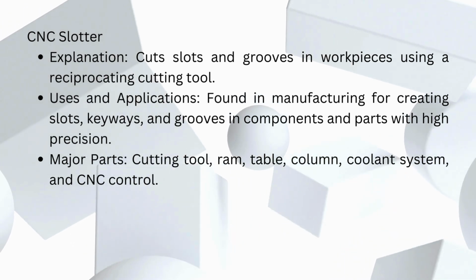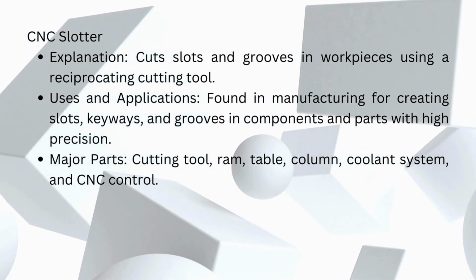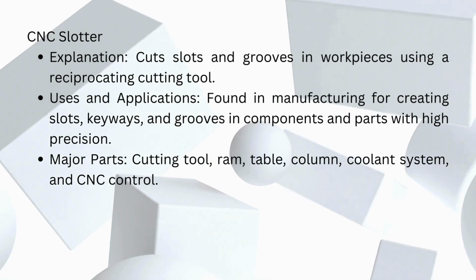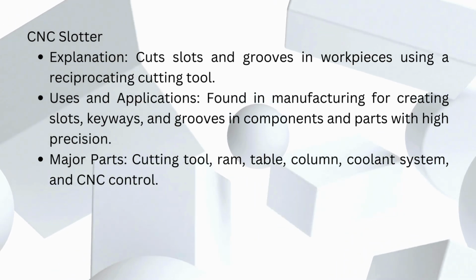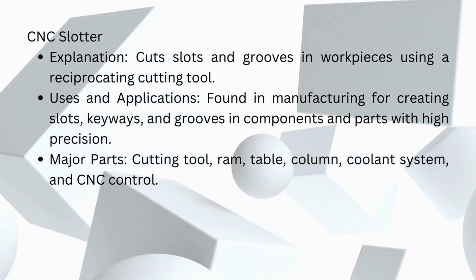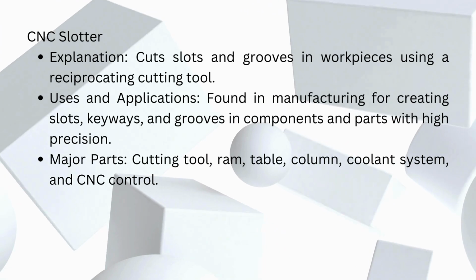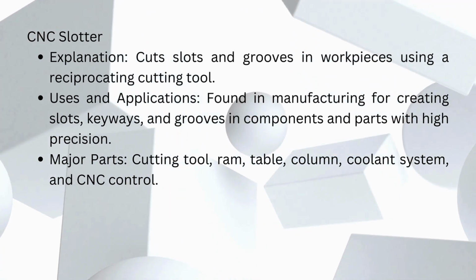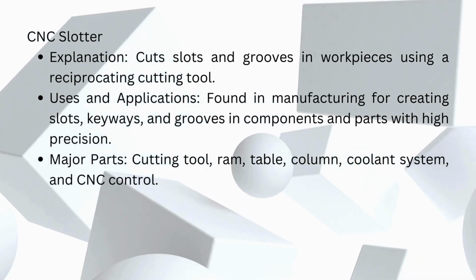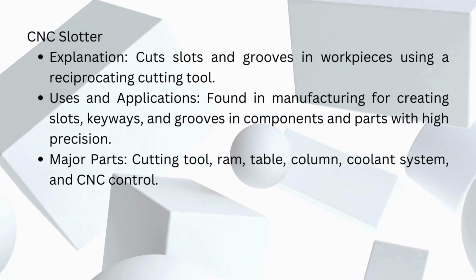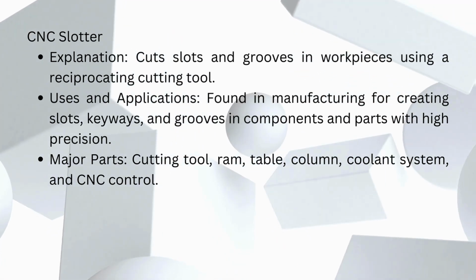CNC slotter. Explanation: cuts slots and grooves in workpieces using a reciprocating cutting tool. Uses and applications: found in manufacturing for creating slots, keyways, and grooves in components and parts with high precision. Major parts: cutting tool, ram, table, column, coolant system, and CNC control.